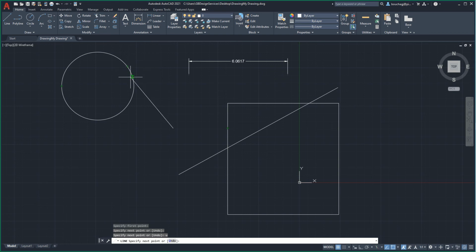The nearest Object Snap recognizes every point along any geometric object and, quite honestly, provides way too much feedback and makes it difficult and confusing to detect other object snaps within your display. The nearest Object Snap should always be off unless needed.